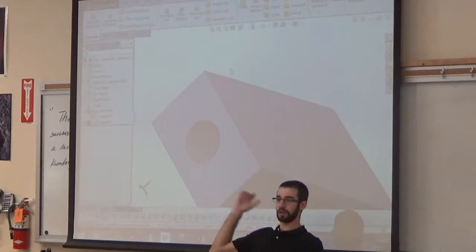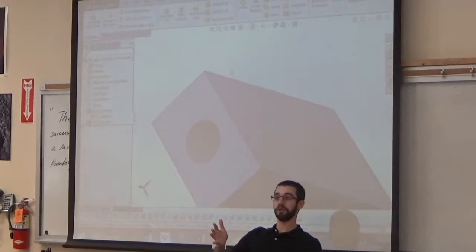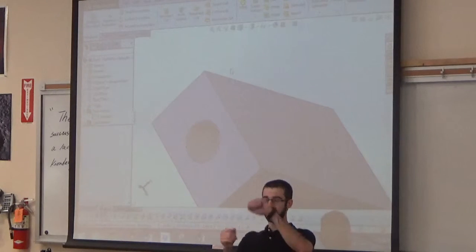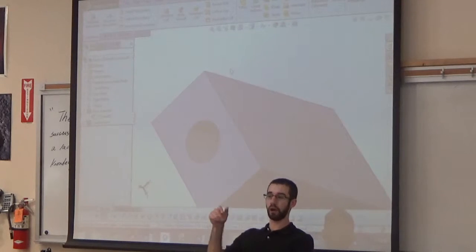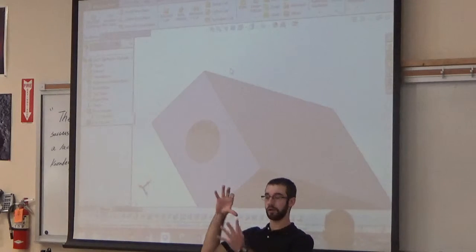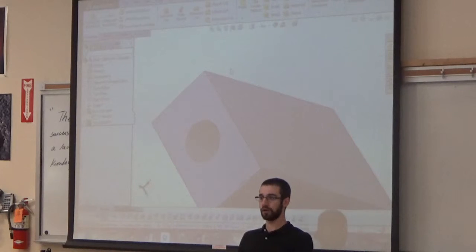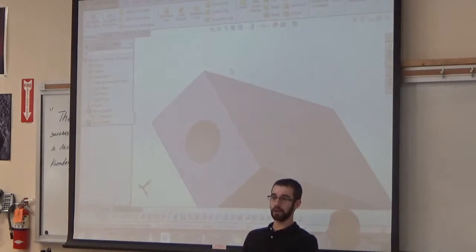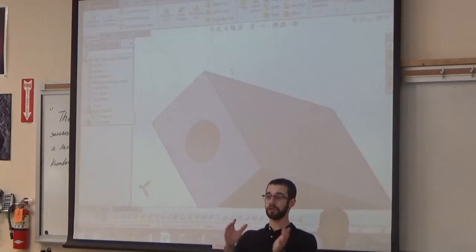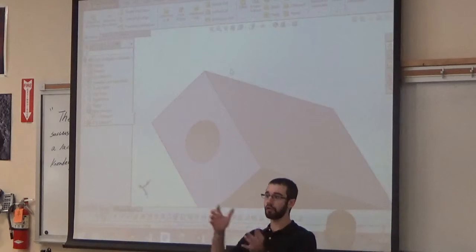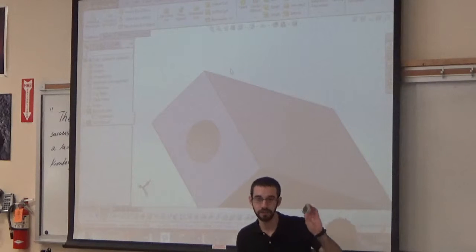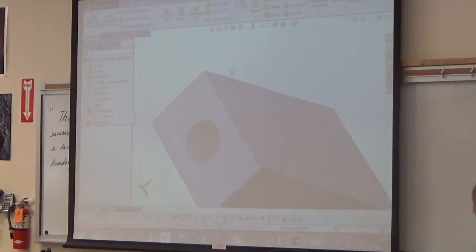Sure. And so there's other things, so you can do wire cutting with it as well. So basically it's a way to automate your process so you don't have the operator at the mill or at the tool doing it over and over again. And it can be expensive just for the more complex part because you have to set up the tooling for it. But in the long run, you're going to have better tolerances on your parts, which means you're going to have basically the same part over and over and over again. So I'm going to pass this around. This is something that was CNC made, CNC cut with a drill.